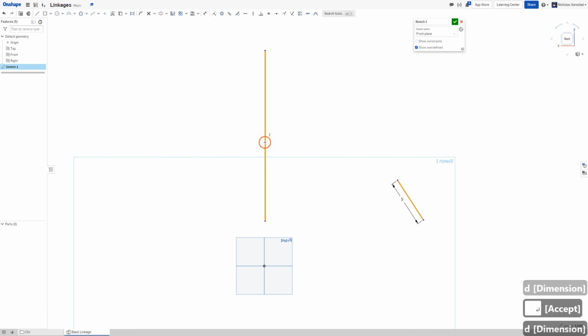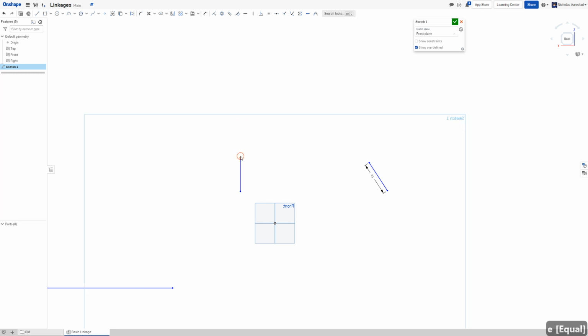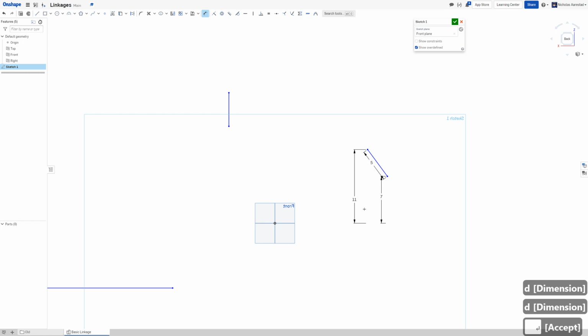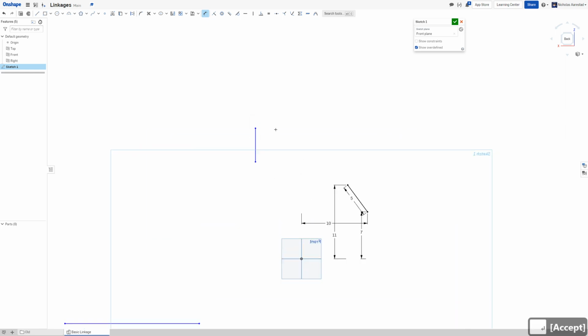Make these guys equal. This is one of the key things about really doing this as well, is about using equality and using geometric constraints in Onshape to efficiently do things. So this is going to be one of our endpoints. It's going to be what I'll call our end position. End versus start is really arbitrary.